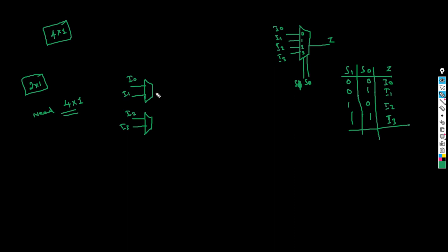Okay, now what about your control lines? Common, only one control line, sir. Common for both muxes. That is going to be S0 or S1. Which LSB one will be given to the first stage of mux. So it is basically S0, is that right?